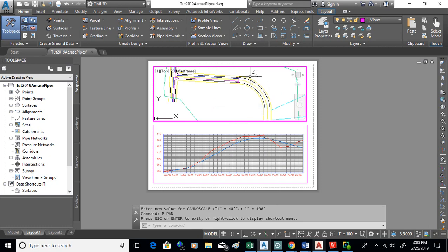Okay, now notice I've drawn a north arrow in here in model space. I've done that on purpose because when I do my Dview Twist, up won't be north anymore. So I like to get a north arrow that shows which way north is on these things. That can be a good idea just to help the person viewing the drawing to stay oriented.